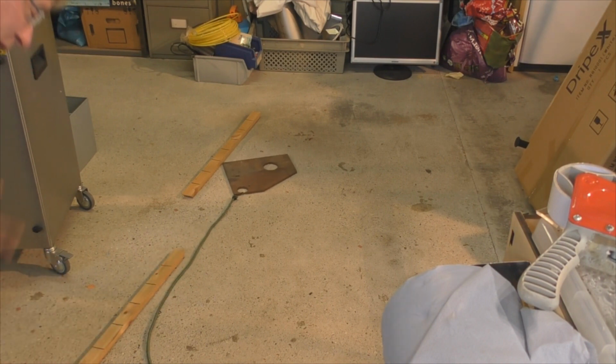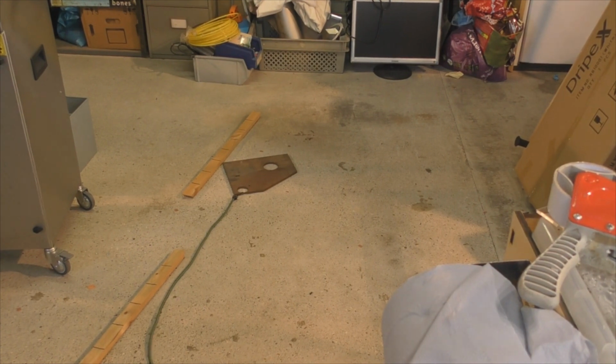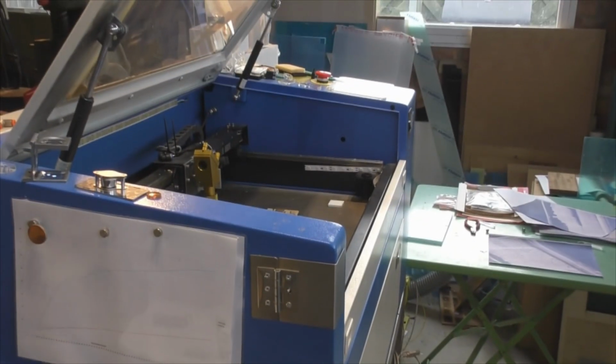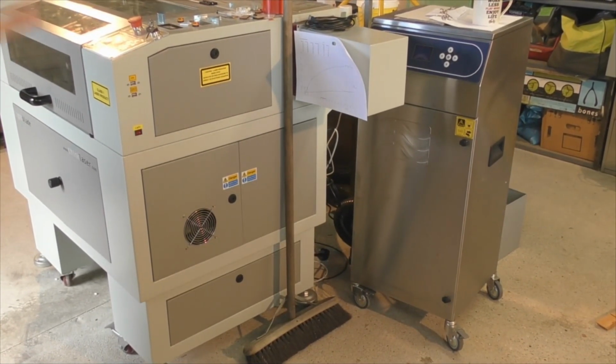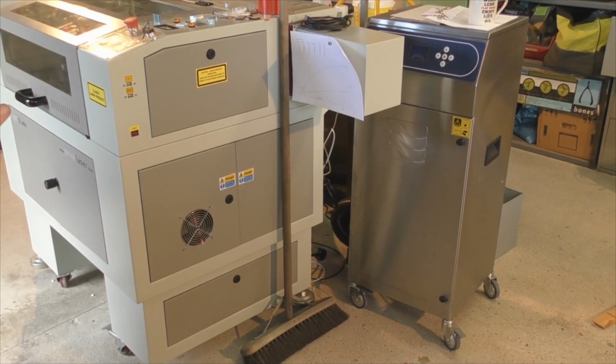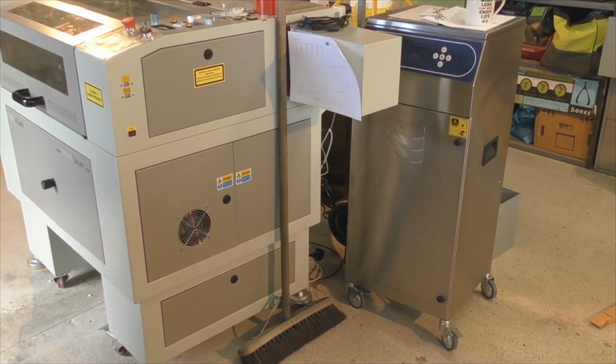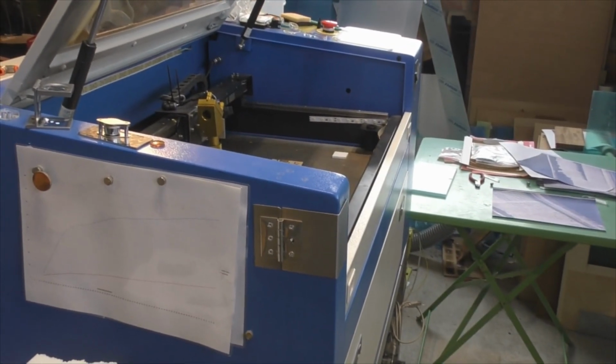So regardless of the number of pulses that the controller has to put out, the command string will not stop until my lump of metal has reached its appropriate point. Now that's the difference between the system on this machine and the system on that machine. This is slightly more intelligent, but at the end of the day it's still a stepper motor driven system with a degree of intelligence, whereas this one is just a stepper motor system with 0 intelligence.